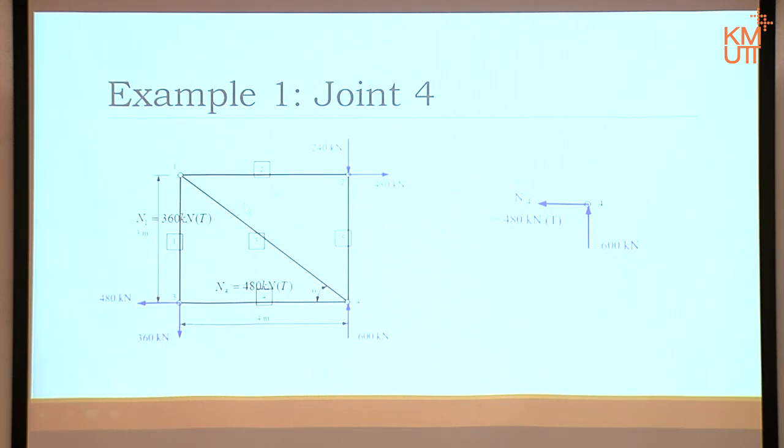This one is vertical. That one is also vertical and horizontal. Meaning in vertical you can't analyze it first. But that one is in horizontal. That one is in horizontal. We can analyze it straight away. Right? So in this case it means that N3 has to go to the right hand side. In this case it means down and right. Correct? In this arrowhead. There. Correct? Yes? Okay. Then we know if it's going that way, tension, coming that way, compression.